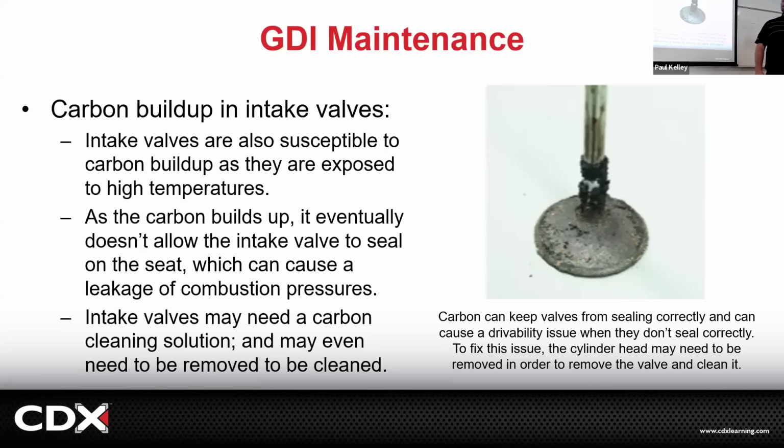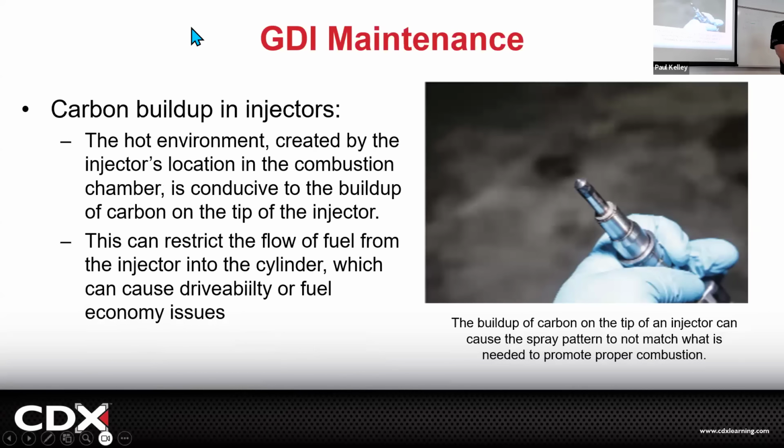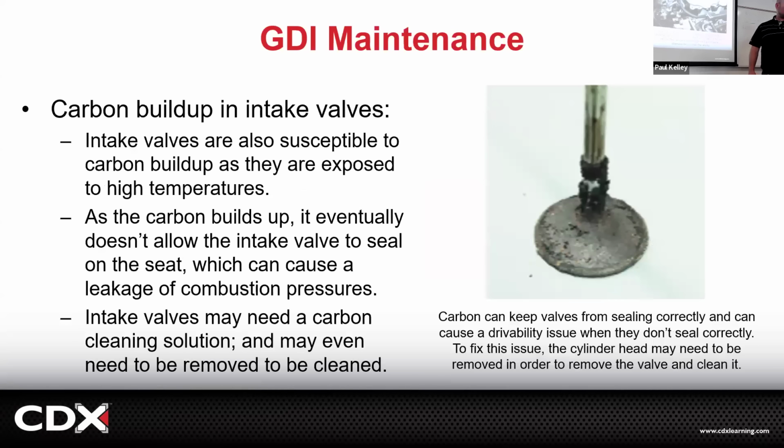I'm just saying, back when it was port fuel injection, we didn't really have this. And on GDI, we do. Sorry to break your heart. And same with the injector, you know, these can get carboned up. These need more maintenance. They're in a harsher environment. They're not chilling in the intake port anymore. They're in the cylinder exposed to the flame. Kind of makes sense? Okay, so here's a crazy idea.